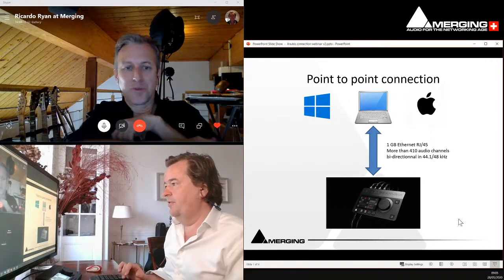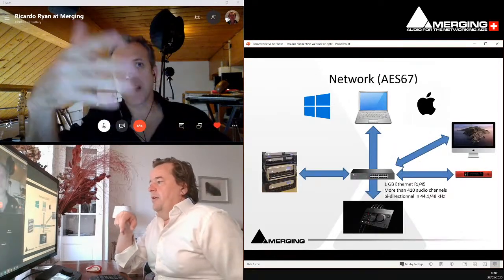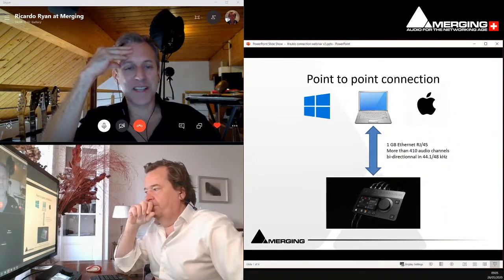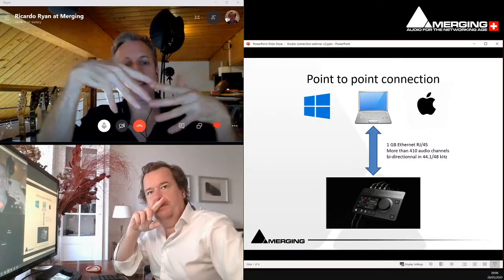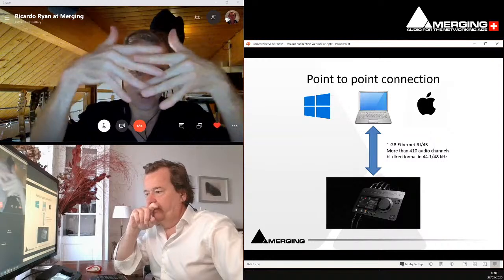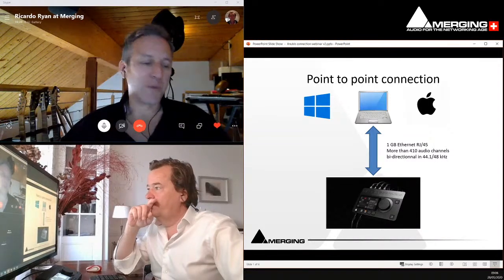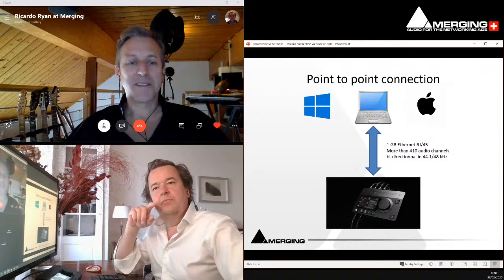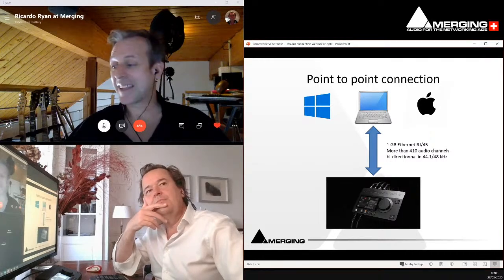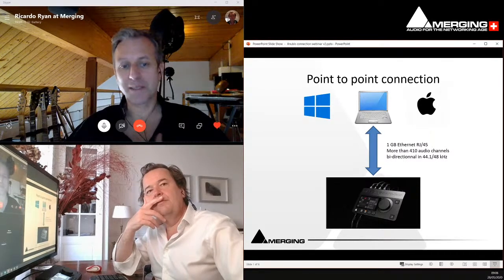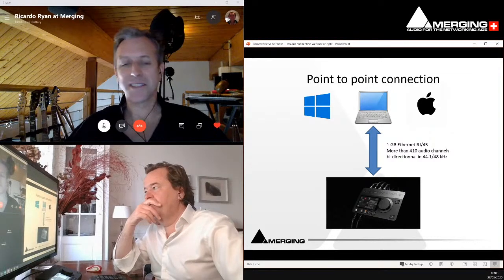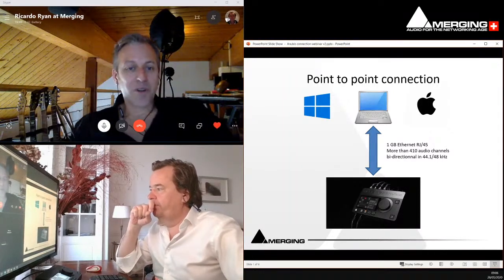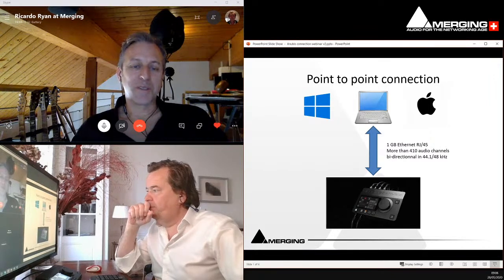I think you can move to the second point. To be clear, about what you were saying about the multiple channels, Anubis does have 256 I/O, and the built-in mixer can mix down 128, if you count the crossfade. So that's why we split the count by half. That's why Anubis actually has 128 channels of Ravenna that can go in and out through the mixer and be mixed within the device itself. And then, as you say, from all those channels, you can decide which of those inputs you want to monitor at any time.